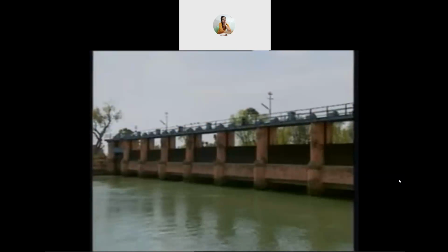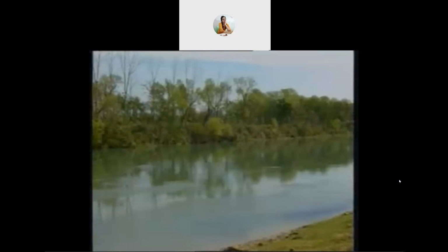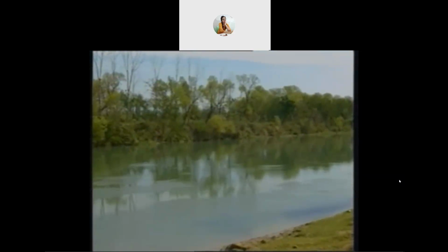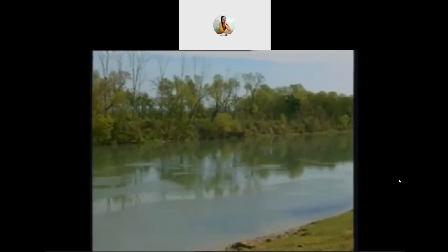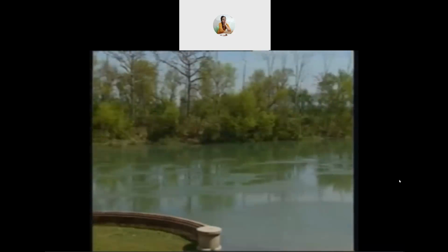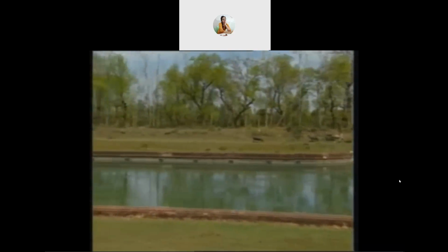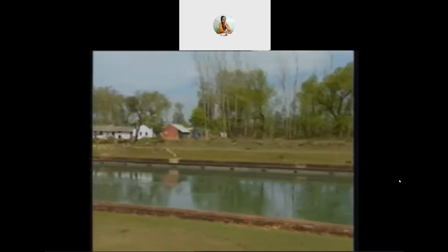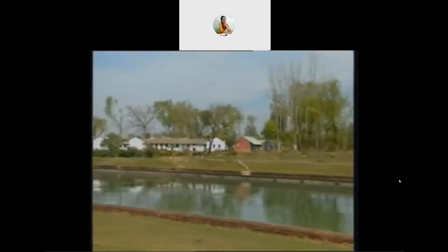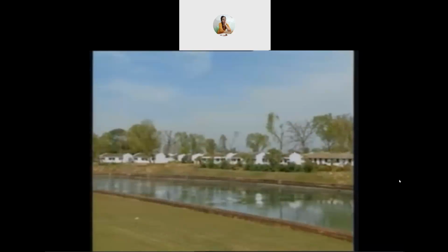The amount of water that we feed in a channel does not reach the fields. A major portion of the water is lost through seepage. The seepage losses constitute 35 to 50% of available water at the canal head. Seepage losses are considerably reduced by lining the canal. Lining also prevents waterlogging, weed growth, and reduces silting and erosion in the canal.